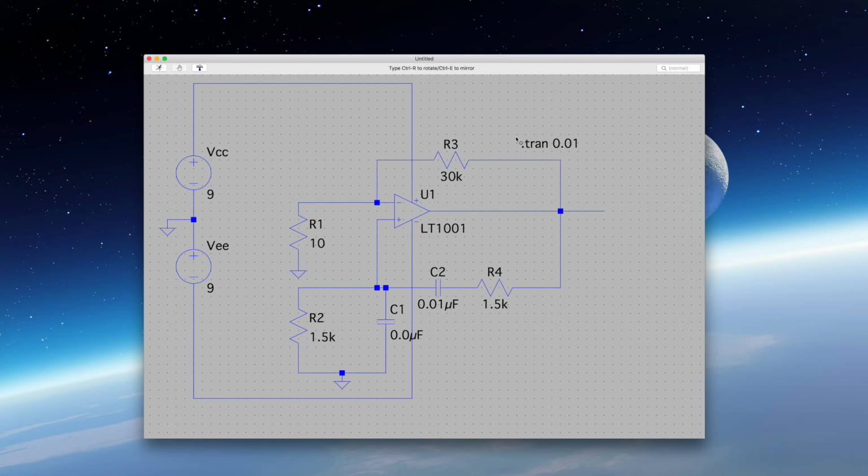And there you have it. So the tran is right there, okay? This is ready to run. What I like to do sometimes is put a label right here where I would want this one to be, let's say, V out, because you're measuring V out versus ground, right? So I'm going to put my probe here. Whatever voltage I get from here is always vis-a-vis ground, either here, here, or here. So these three prongs here are all connected to the battery where the two batteries connect, the minus and the plus connect together, okay?